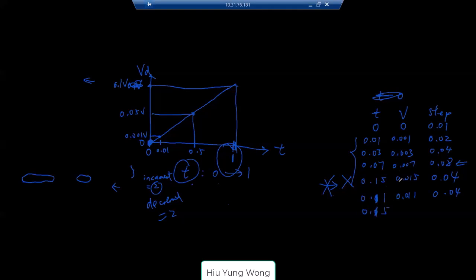Then now I go to 0.15 again. This time, because I have a good guess solution, so maybe I converge, right? And then I can continue. And maybe it suddenly converges very well. Then I'm going to double again. And that's how it does the simulation.